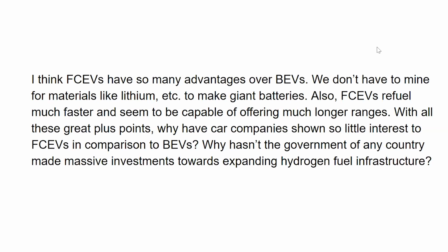But when it comes to fuel cell electric vehicles, you first have to use some methods to produce hydrogen, then you transport hydrogen, then you pump hydrogen, and you convert hydrogen back to electricity, and then you use that electricity to charge the lithium to run your electric motor. So overall you have some efficiency losses in a fuel cell electric vehicle compared to a battery electric vehicle. But having said that, it has many advantages, like it says over here that it can refuel quickly and it can have a good long range as well.